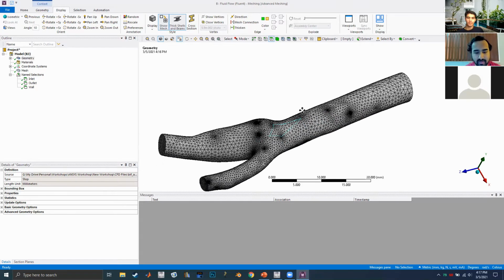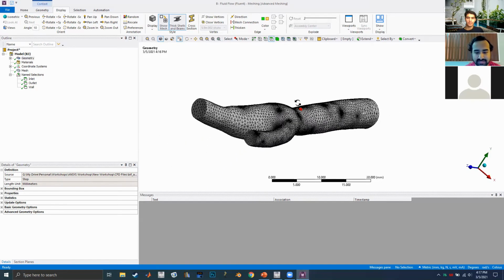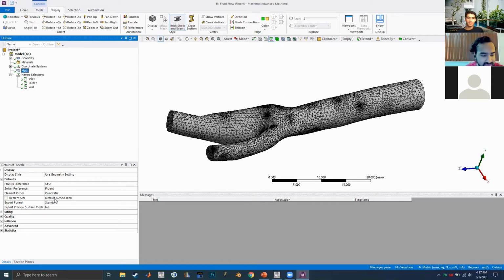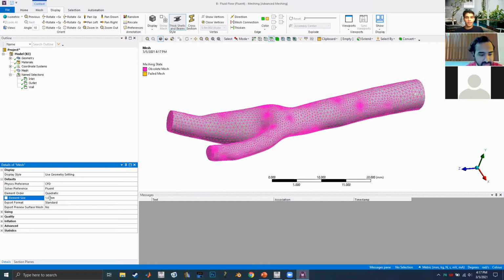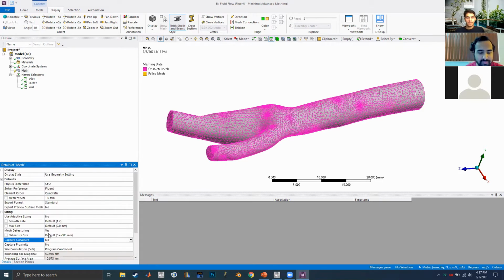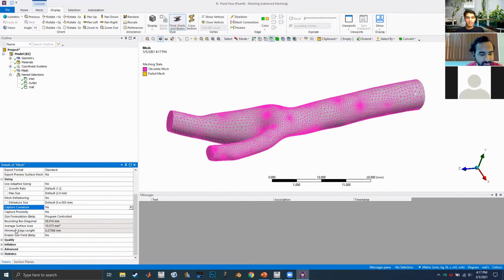So now is where we don't trust Ansys and we go based off our own intuition on how to make the model. So what I say first is dump this down to perhaps 1 millimeter in terms of your mesh size. And for sizing, turn off capture curvature. If you turn off capture curvature, it won't try to capture these strange points of discontinuity here.